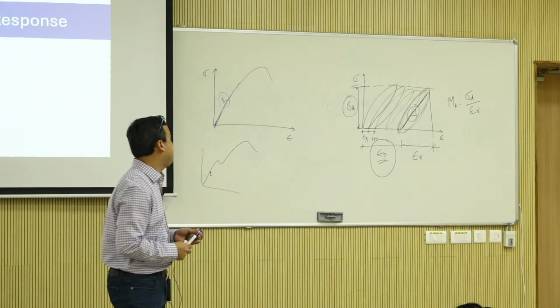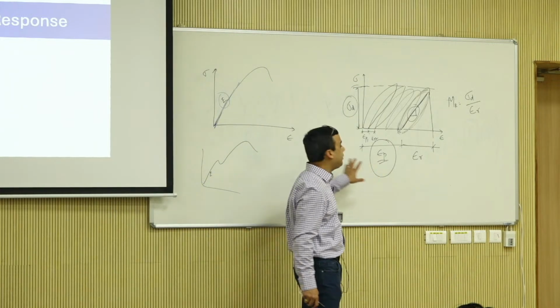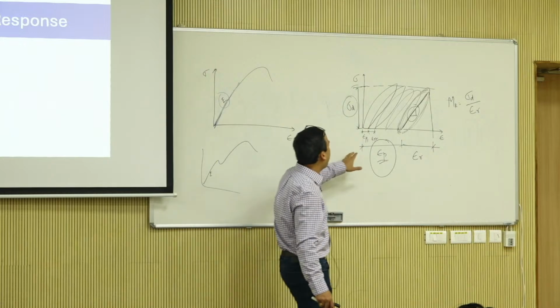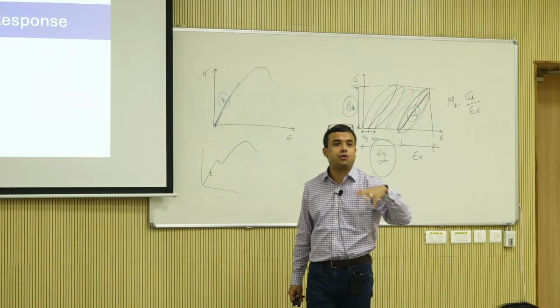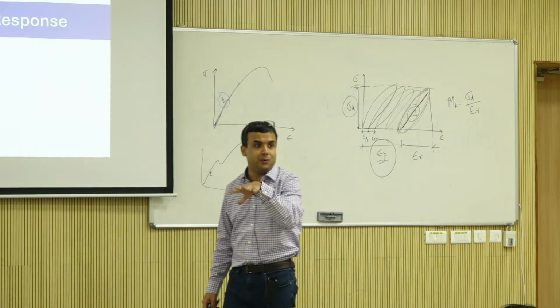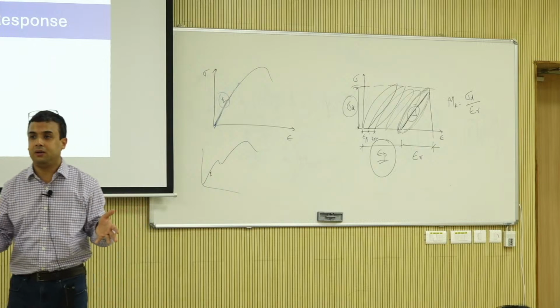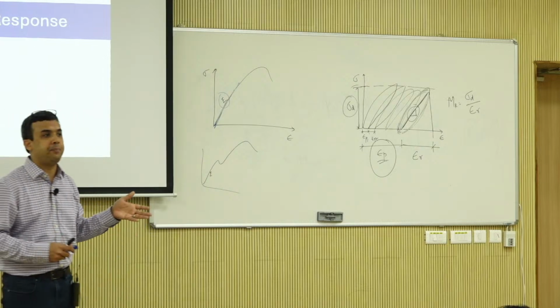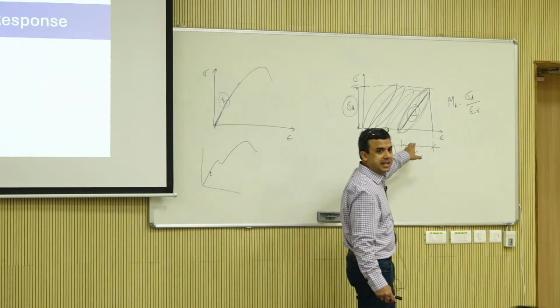Ideally, if you have a really well designed and well constructed pavement, you should have all your permanent strains accumulated. That's what's called the conditioning of the sample. We'll get into that. Some people call it shakedown of the sample before you hit the resilient part.